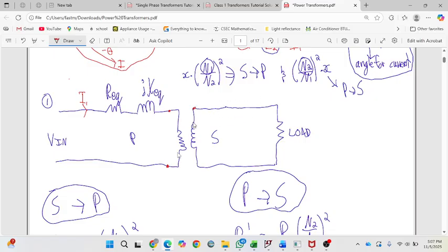So if you use your turns ratio and you get 223 volts here, that will be the voltage at the output because there are no more losses, because I already accounted for them on the primary side, which is the beautiful part of it. So once you get this E1 here, you're kind of set, because once you use your turns ratio on it, you're already getting your output voltage because it has no impedance. The secondary, because you referred it to the primary, means you accounted for it already, so you don't have to worry about it too much.